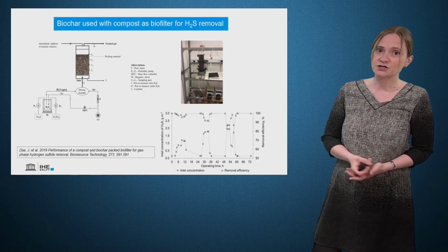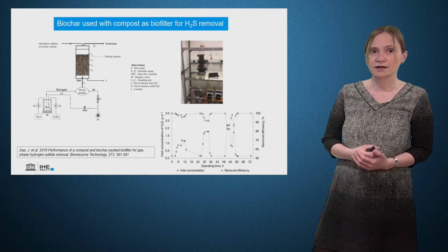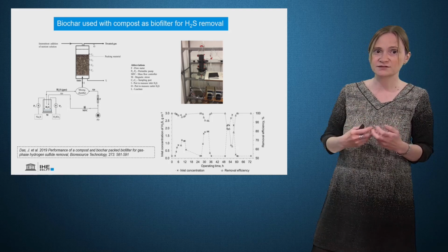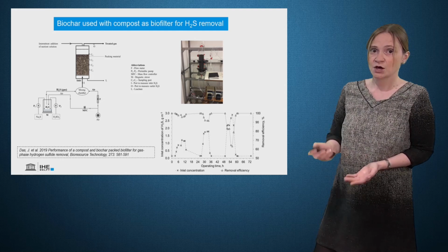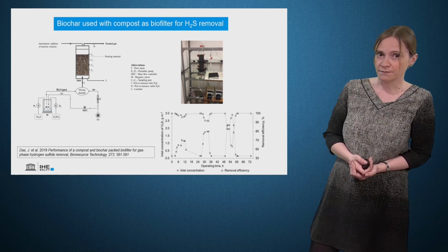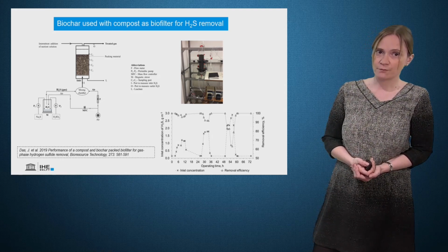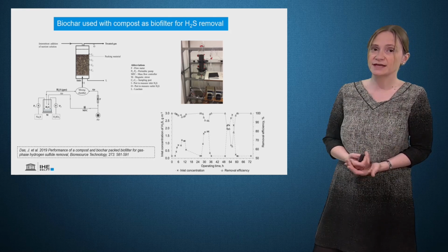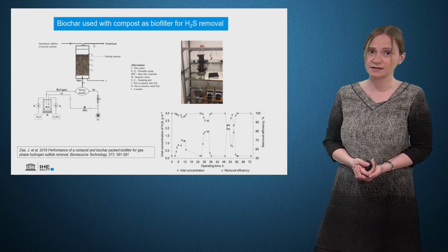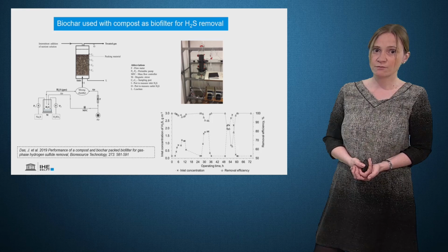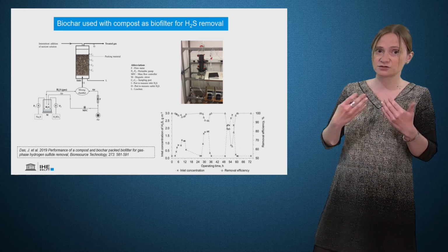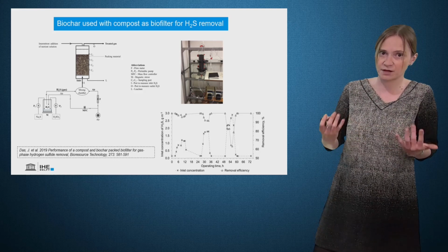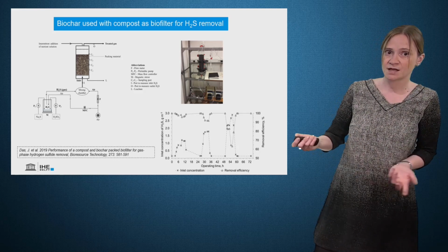The second application is in gas, where biochar can be used to remove H2S from biogas exiting a digester, for instance. Biochar can be used alone or in combination with compost in a biofilter. A study has, for instance, been carried out recently here at IHE, and the results have shown the increase of efficiency when biochar and compost act together rather than when compost acts alone.